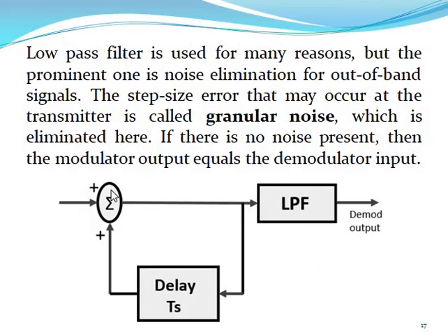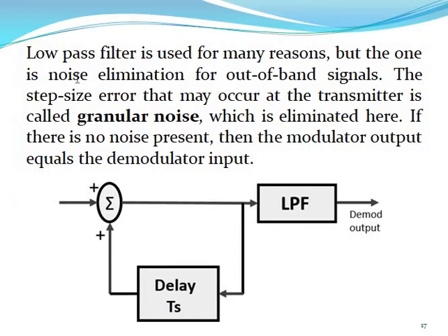So you can add delay also. The low pass filter is used for many reasons, but one is as a noise eliminator for out of band signal. The step size error that may occur during transmission is called granular noise, which is eliminated here. You can show the inputs and outputs here, and finally the low pass filter gives the demodulated output.